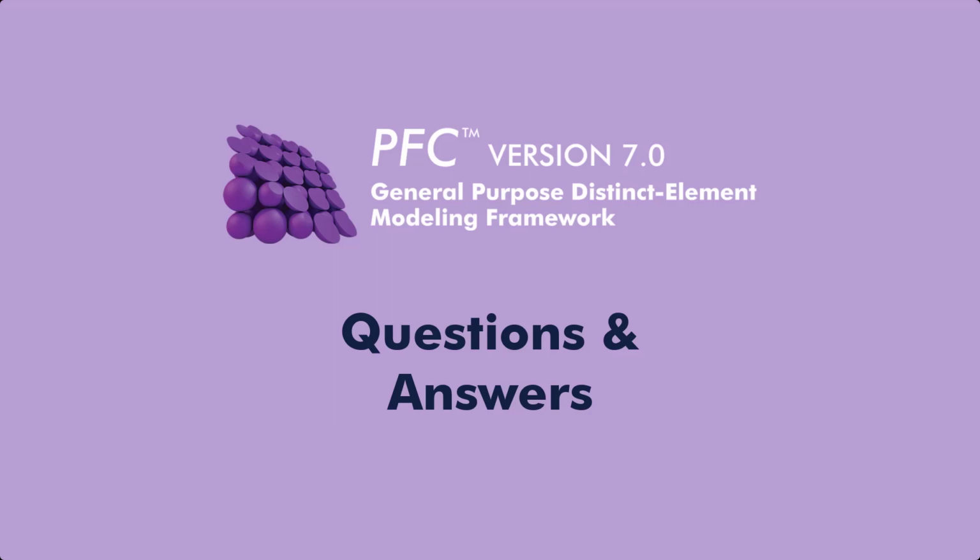Is it possible to create a porous medium with non-overlapped connected balls with PFC abilities such as tessellation, where the dimensions of the medium, radius, and number of the containing balls for creating the model are specified? If I understand correctly, you mean pack an assembly of balls and then use this information, so the position and the size of the balls, to actually inform the tessellation. And yes, this is possible.